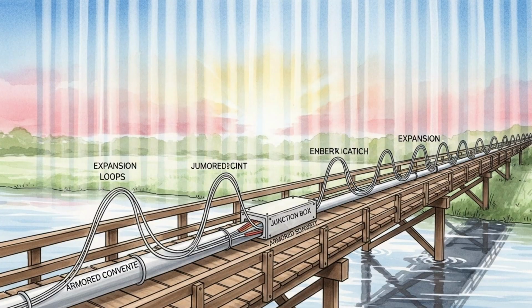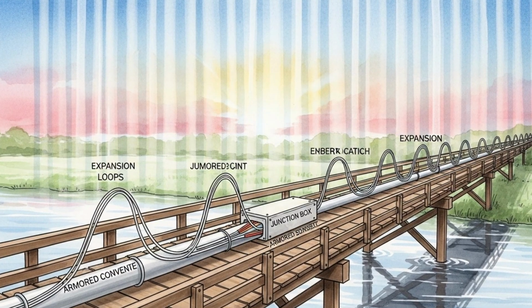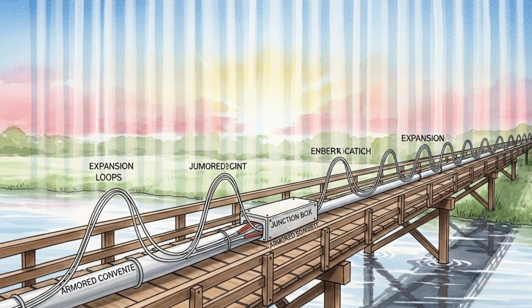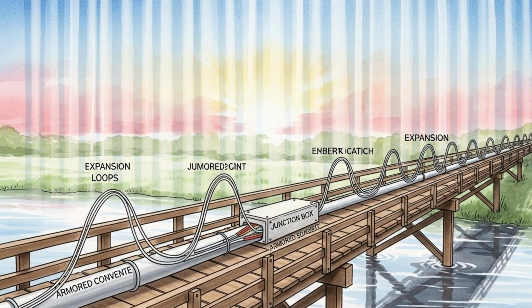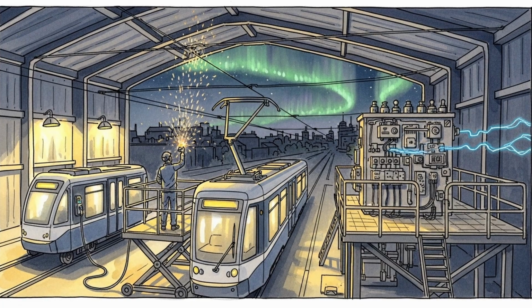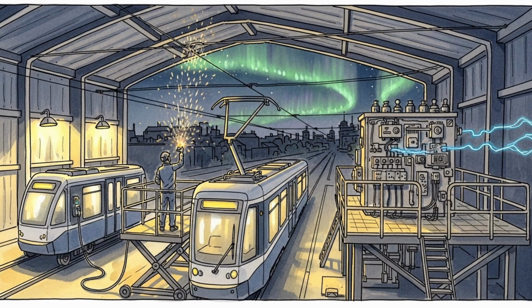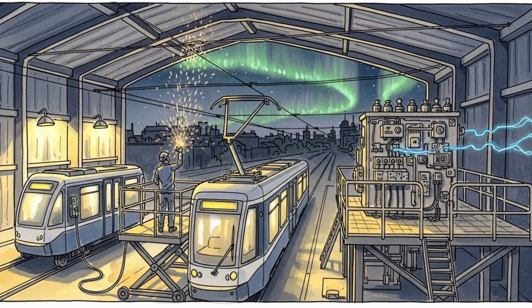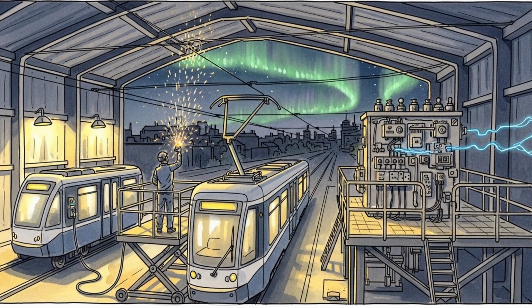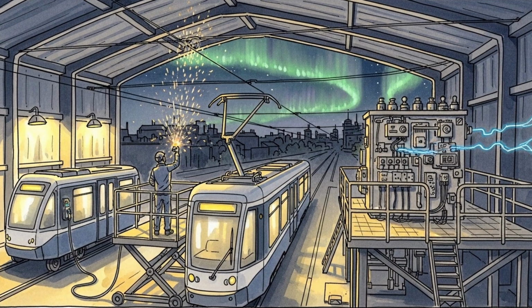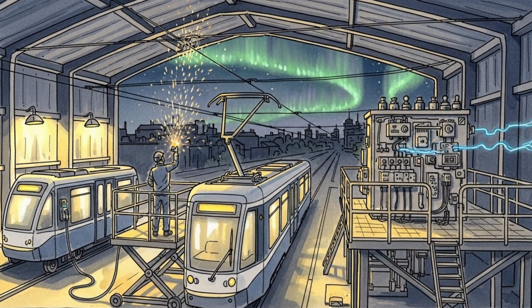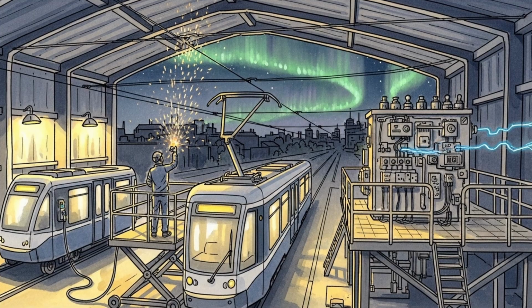Space segment and navigation recovery. Increase orbit determination until drag returns to pre-event levels. Update two-line elements or precise ephemerides with higher cadence. Perform maintenance burns to recircularize shells or maintain altitudes. Reacquire lost spacecraft and verify health. Restore payloads from safe mode in steps.